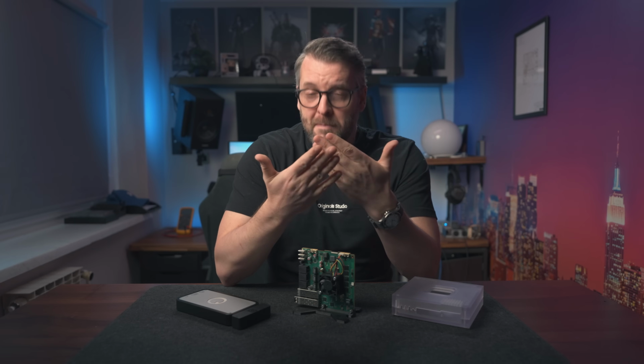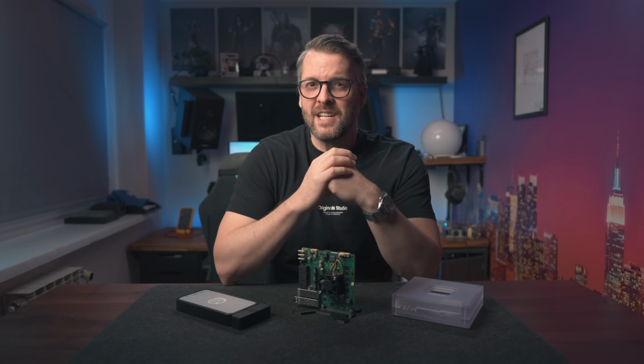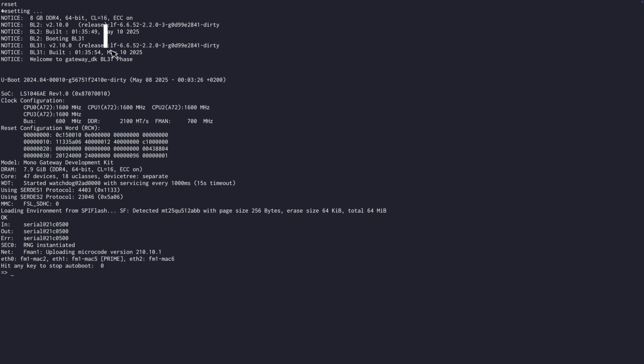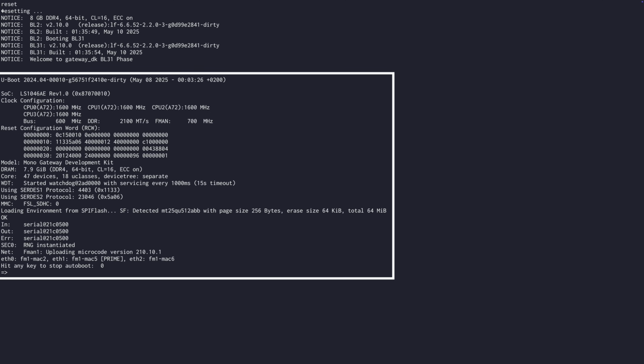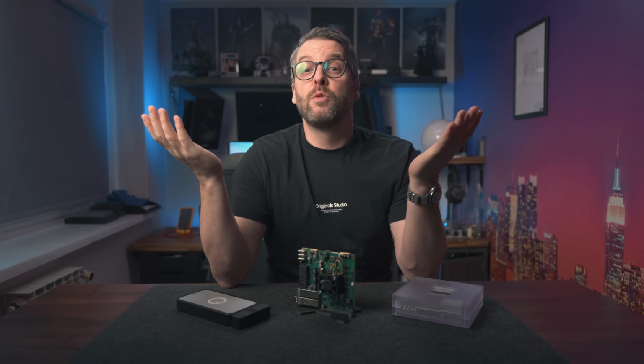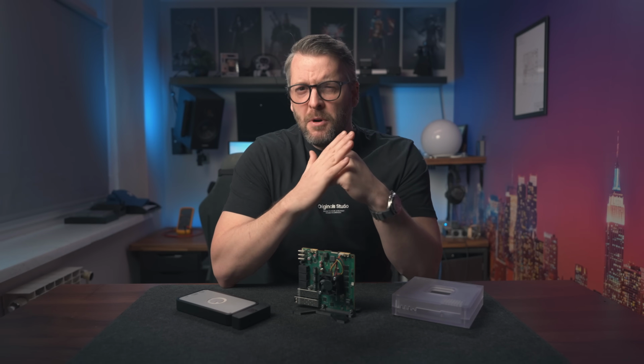The primary purpose of this BL2 firmware is to configure the memory controller, and once it's done with that, to copy the BL3 firmware that's normally stored on the same chip as BL2 into now running memory, and finally execute this BL3, the main part of which is the first interactive piece of code that you probably heard of before, U-Boot. And yes, that does mean that in order for U-Boot to run at all, you need, well, working memory. Which almost looks like a